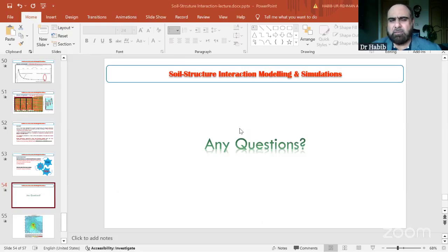But basically, if you ask me, it's in no comparison to the real soil behavior. Soil is a continuous medium. Even if we bring soil springs closer to each other, there will be no lateral connectivity among these, and each spring is acting independently. If we connect these springs together, we are a step towards soil continuum, but not even close to it.